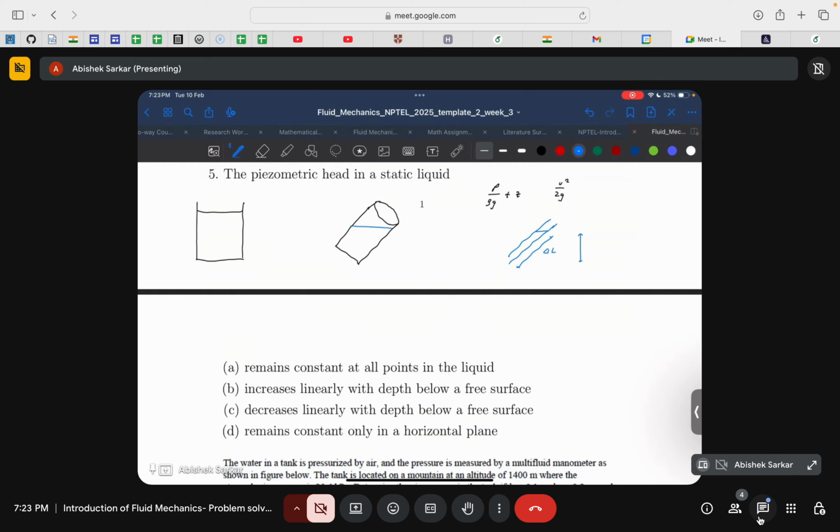But the eventual measurement of the pressure difference is in terms of the vertical deflection, which is delta L sine theta, so delta S becomes equal to delta H. So the pressure difference is always measured in terms of the vertical height, not the slanted plane or the horizontal surface. Even if your plane tilts, the pressure measurement will only depend on the vertical height, not the inclination of the plane on which the liquid is contained.